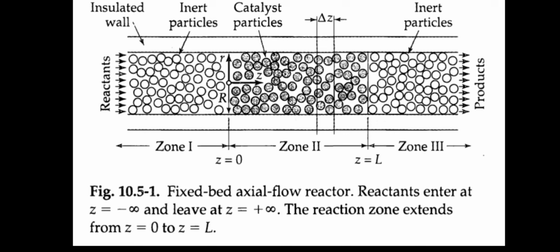This zone might serve to cool down the product stream or to ensure a more uniform temperature profile at the reactor outlet. It's vital to understand the spatial arrangement of these zones. They are sequential along the axial length of the reactor. The fluid stream first enters zone 1, then flows into zone 2, where the reaction occurs, and finally exits through zone 3.